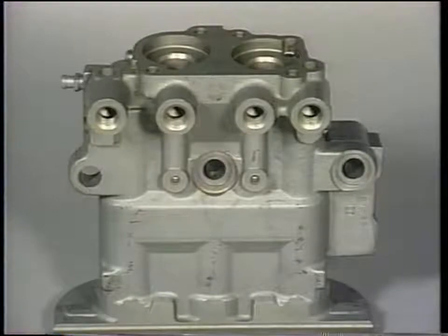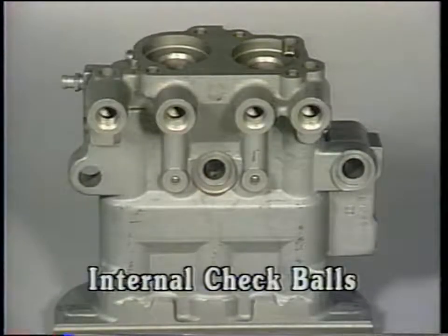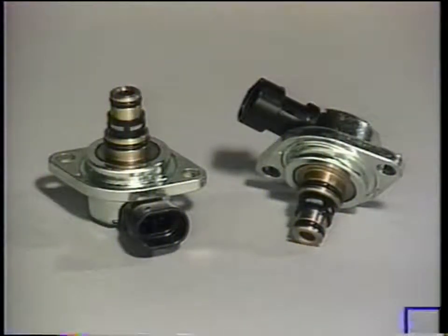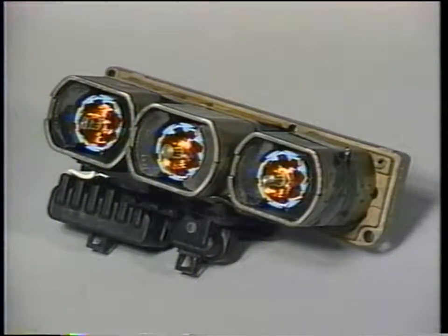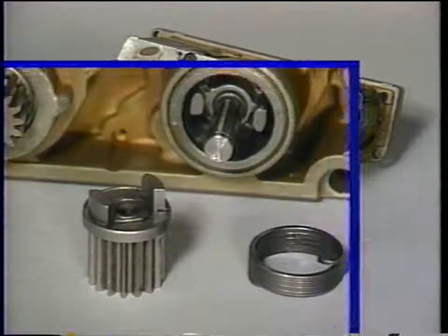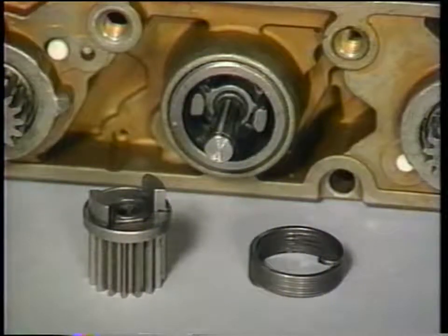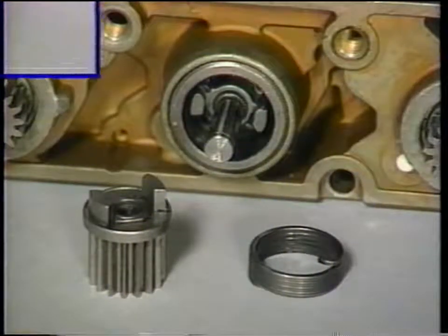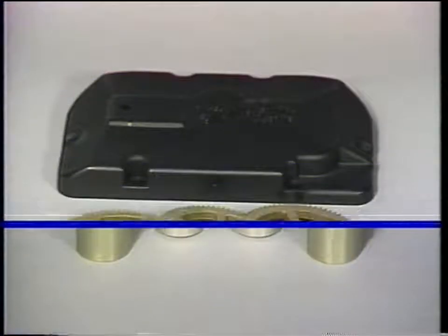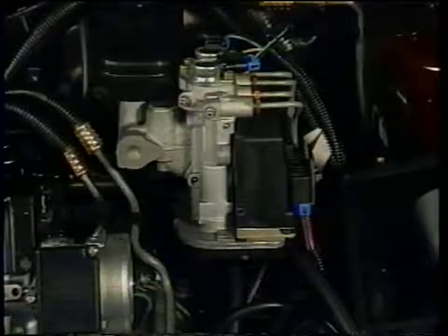The modulator assembly consists of fluid chambers for all 4 brakes, 4 internal check balls, 2 isolation solenoid valves, a motor pack containing 3 bidirectional direct current motors with electromagnetic brakes, or EMBs, and/or expansion spring brakes, ESBs, 3 ball screw assemblies, 4 pistons, a gear drive set, and gear cover.